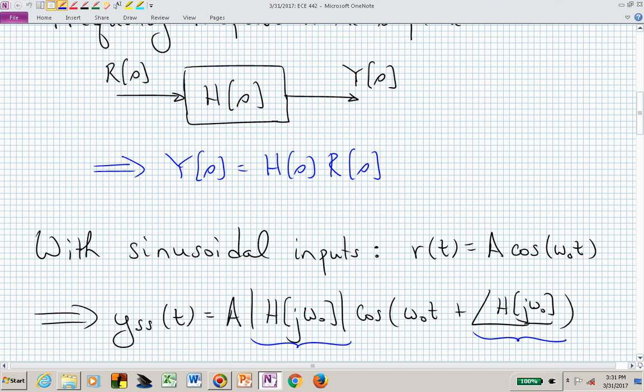If we apply that to this linear time invariant system that now is modeled or represented as a transfer function capital H of S, then we can find the sinusoidal steady state output, or what we know is if we're shaking that system at a frequency omega naught, then the output of that system will be another sinusoid at the same frequency, just with its amplitude modified and its angle or phase modified or shifted in time as what that angle represents.